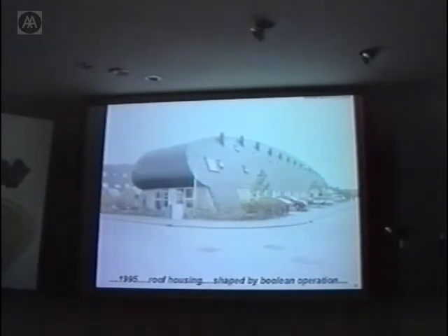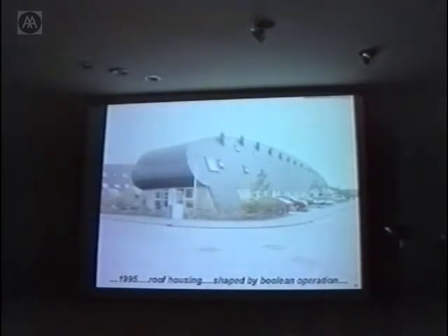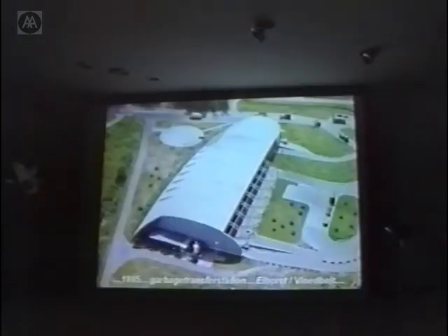What we did here was we had an oval shape extruded in one direction, say the X direction. We had a triangular shape extruded in the Y direction, and we intersected them. If you know 3D Studio or AutoCAD's AME module, you know about these operations. You can also join them, and you can also subtract them. So here we calculated what these two bodies had in common.